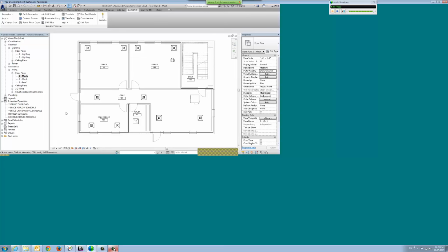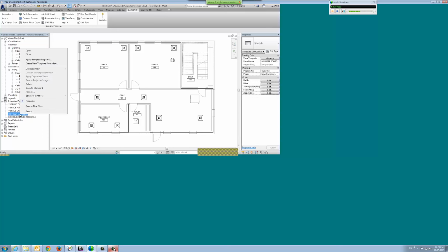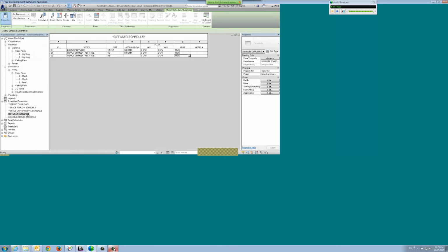If I'm going through and filling out a sheet index or sheet names, sheet numbers, I can export that information out as well. That's an exportable category for me. So I can do all my typing inside of there as opposed to potentially working through one of these schedules, or doing a lot of right-clicking, renaming, and things like that.